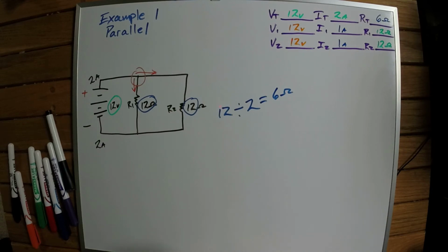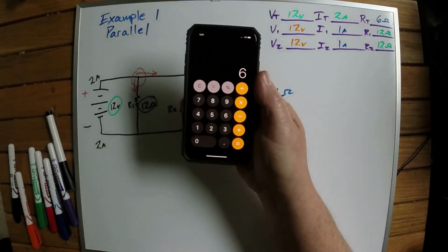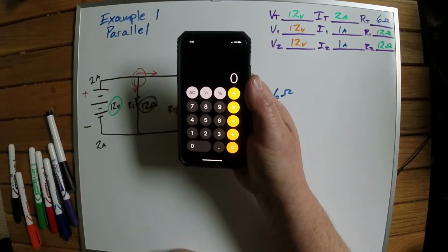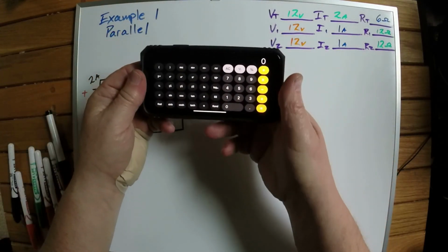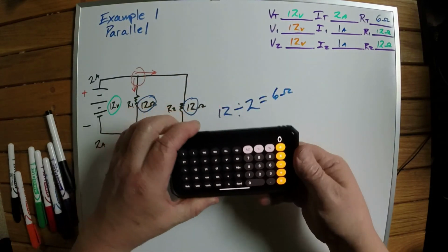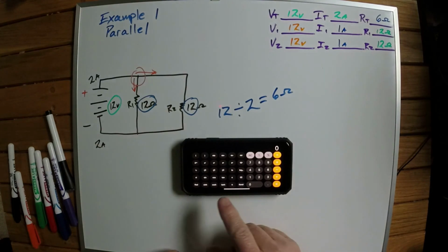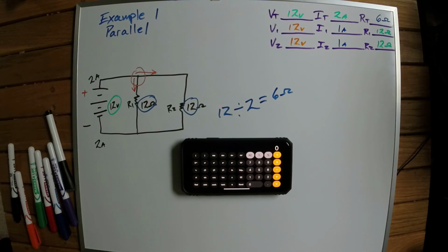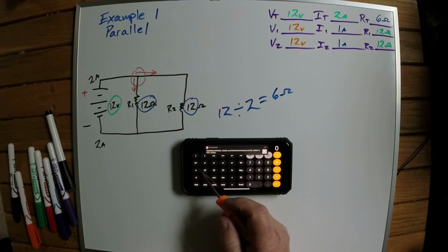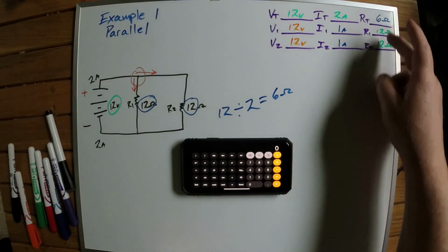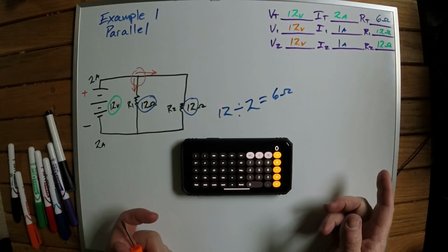scientific calculator. So if you have access to a scientific calculator, we all have our cell phones. And so if you take your cell phone and pull up the calculator and then turn it sideways, you have a whole bunch more stuff that shows up on your scientific calculator. And so if we do that, if you look around here, if you've got a 1 over x key, so in this particular case, I know you can't see it very well on the video, but there's my 1 over x key right there. So I can easily add up my resistance using the reciprocal sum with a 1 over